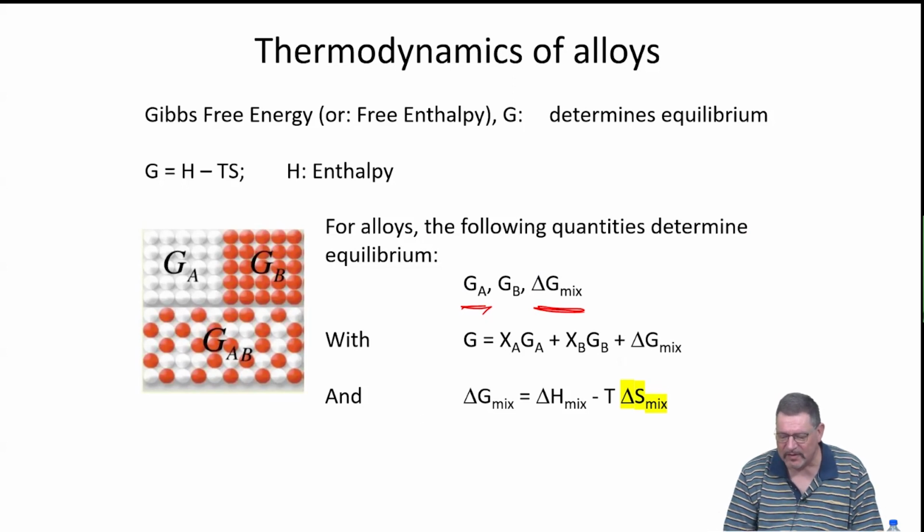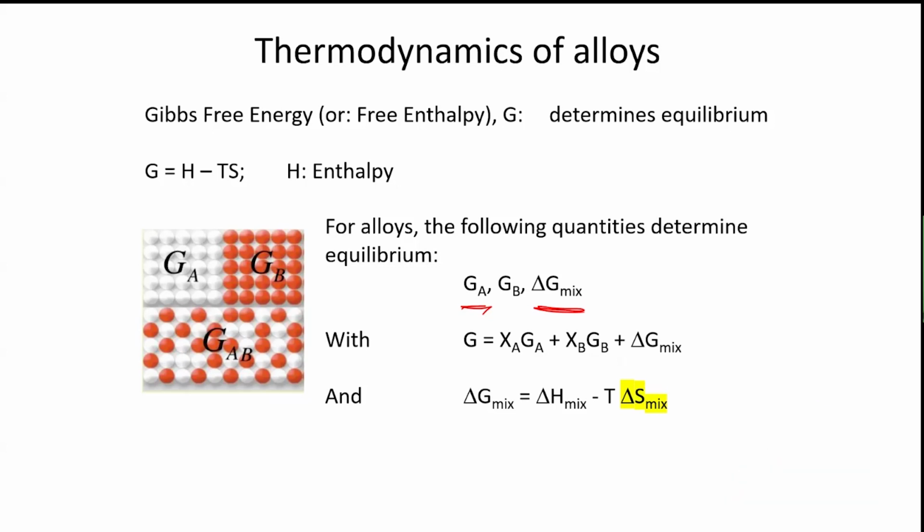And obviously we calculate, when we now mix the two quantities of A and B, then we get a joint free enthalpy curve, free enthalpy functional, which consists of the fractions of the pure states plus the mixing term. The mixing term is this important part where the enthalpy of mixing and the entropy of mixing, the latter multiplied by the temperature, enter the equation.